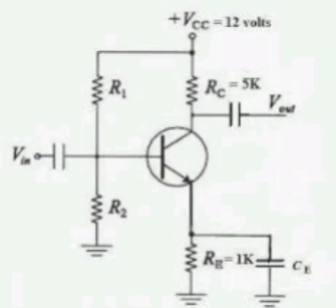Next, 16 volts in series with 4 ohms, in series with j3 ohms in parallel with minus j6 ohms, that is VTH. VTH equal to 16 into minus j6 whole by 4 plus j3 minus j6, where 4 plus j3 minus j6 is the denominator. That equals 19.2 at an angle of minus 53.13 degrees volts. Now the circuit is 19.2 at an angle of minus 53.13 volts.